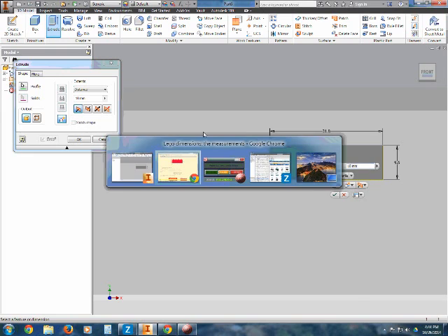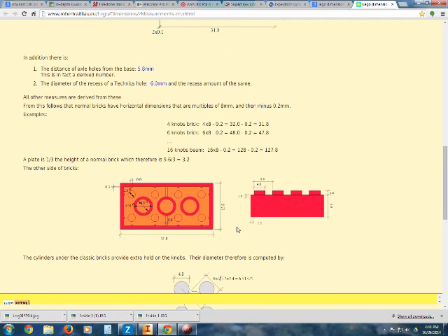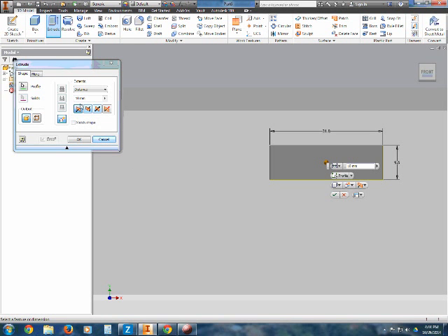Okay, so let's go back and see what our extrusion is going to be thickness-wise. Right here it tells us the distance from the front to the back of this is 15.8 millimeters. So in this particular case, it automatically chose my profile for me. It was the only thing that was drawn on the screen. And distance should be the default under extents. I want to extrude it back into the screen, and I'm going to change the text in there to 15.8. And then click on OK.